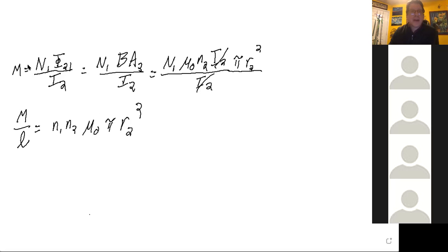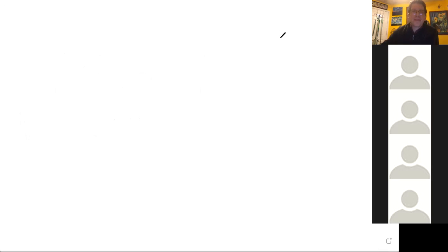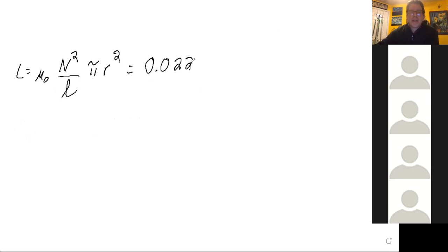I can. Okay. Right, so you're just trying to find the inductance of the solenoid. The formula for that, I'll wait for you to go ahead. All right, the formula for that is L is equal to mu naught times the number of turns squared times the area over the length. Right, you got it. So you input the values that are given by the question and you solve for inductance, which is 0.022 henries.